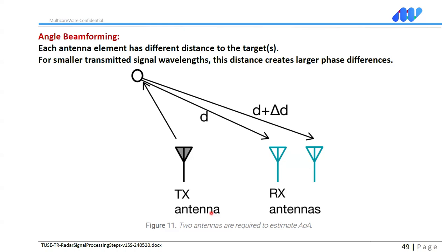If you calculate target azimuth and elevation separately, then you get detection not in 3 dimensions, but you now have 4 dimensions. So your data cube is 4-dimensional. And if you want to add the amplitudes, then you get the 5th dimension. So some radars say we do 5th dimension. It means we are giving more information.